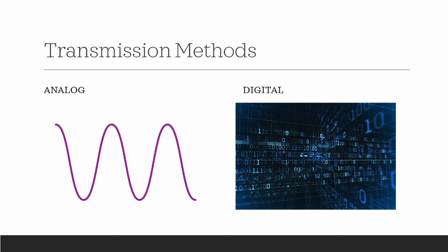If you're looking at a spectrum analyzer, and we'll show more of this in the next video once we get into deployments and do some actual readouts, basically you'll see your two peaks for your two main channels. Then as you bring those transmitters closer and closer together, you're going to see other spurious signals show up on your analyzer, and that creates all sorts of problems for interference and issues that you can have while you're trying to do deployments.